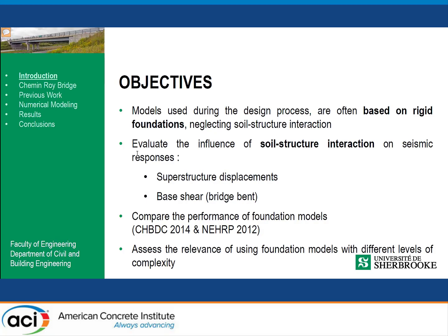So the purpose of this project was to compare what it is worth to model some simplified substructure model, and what the impact of that is on the superstructure and on the base shear of the bridge bent. These are two simplified linear models, one with and one without damping.